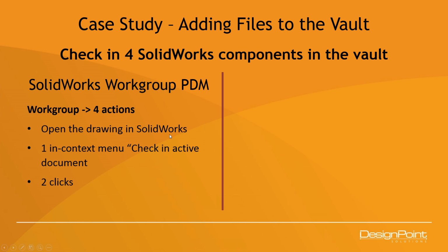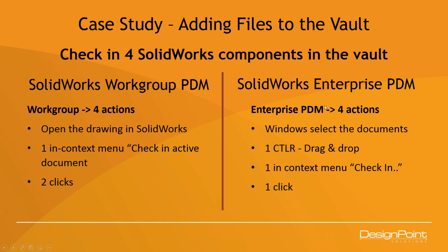So basically, you have to open the drawing in SolidWorks, check in active documents, two clicks, and it's about the same thing for Enterprise PDM. You have to select the files, copy them, right-click on the files, and check them into the vault.